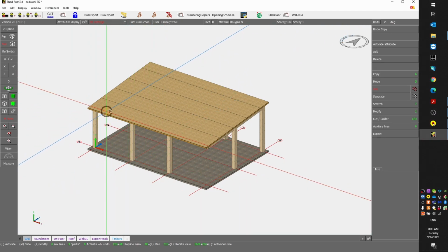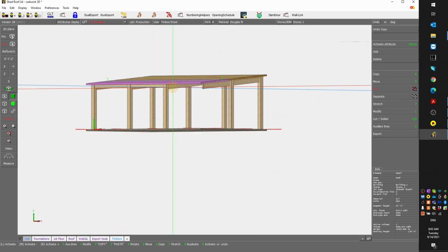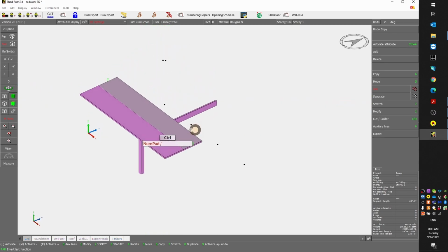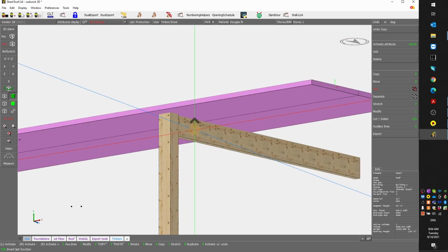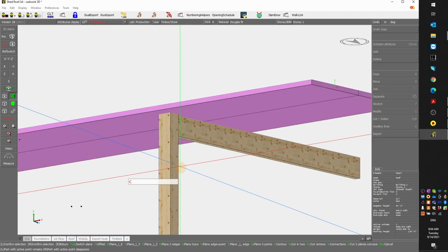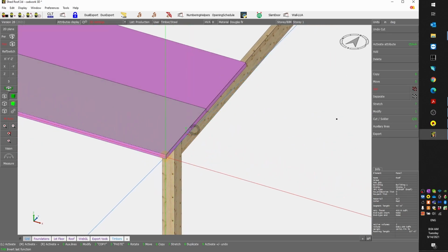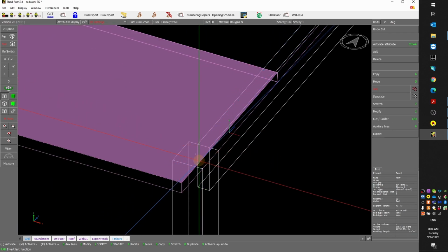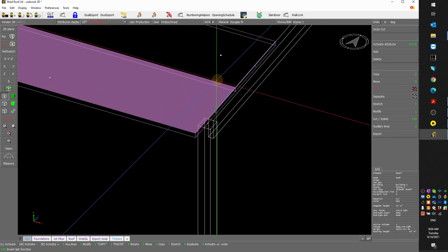I'm gonna pick the first two panels. So left click, right click, and let's take these guys, and two options. I can either cut them against, so that's what I'm gonna do, C to cut, and I'm cutting them. It's actually, yeah, it's 2 feet from the center line of the column. So here CX, and then 2 feet.